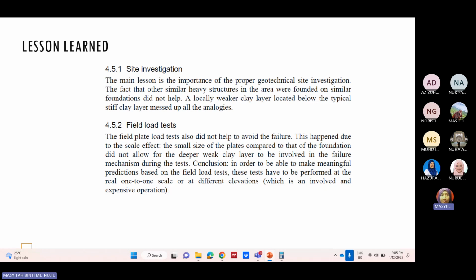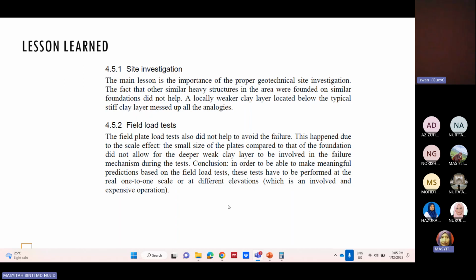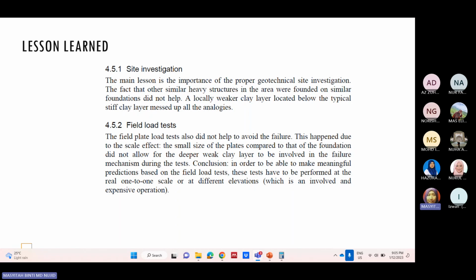From this borehole report it mostly tells you the soil properties, either index parameters or what are called mechanical parameters. Usually the most important in a geotechnical application is the mechanical parameters. Mechanical parameters, for example cohesion, for example internal friction angle. If it involves excavation, or you want to construct a road on soft soil, then we will have a trial embankment.